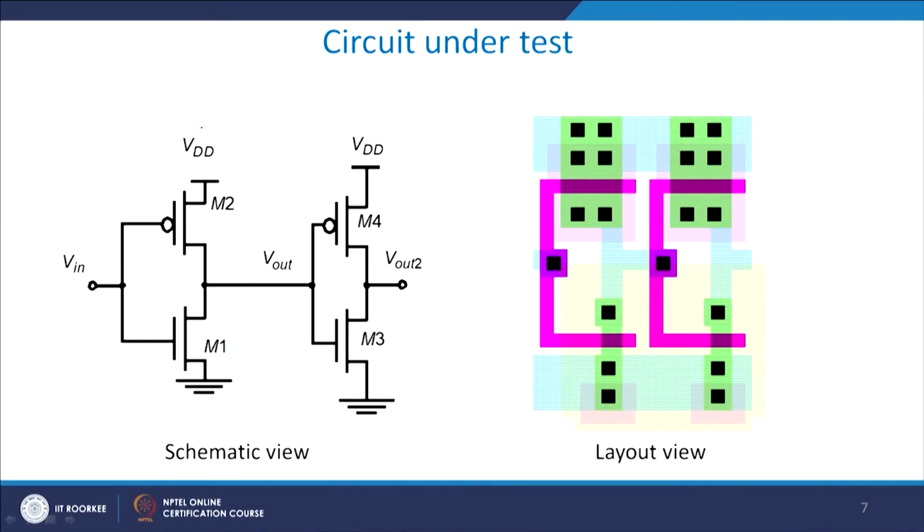So look at the second test, as you can see I have got two CMOS inverters driving each other. This first one is, let us suppose, Q1, and the next one is Q2. So Q1 is driving Q2, and as you can see here very interestingly you have a contact here, this contact is this one, and when the poly layer and the metal layer cut, this is your MOS device.